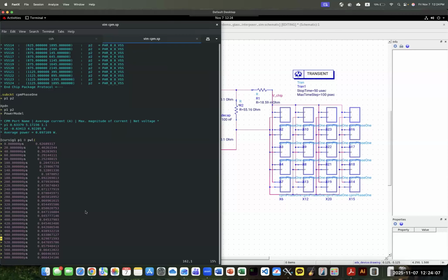We can do the different frequencies as well, and keep in mind that when activity stops, the ground will bounce, because that energy goes into ground. And ground is common for all the chiplets. So when you fire one up or off, you have these discontinuities, which could be interesting.